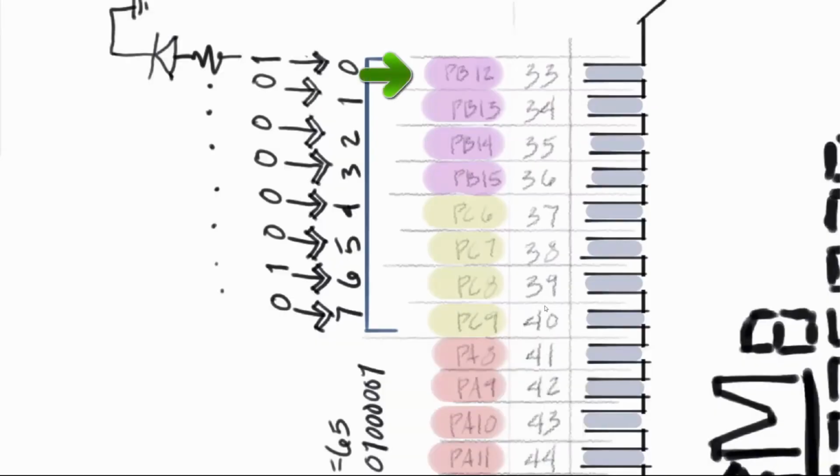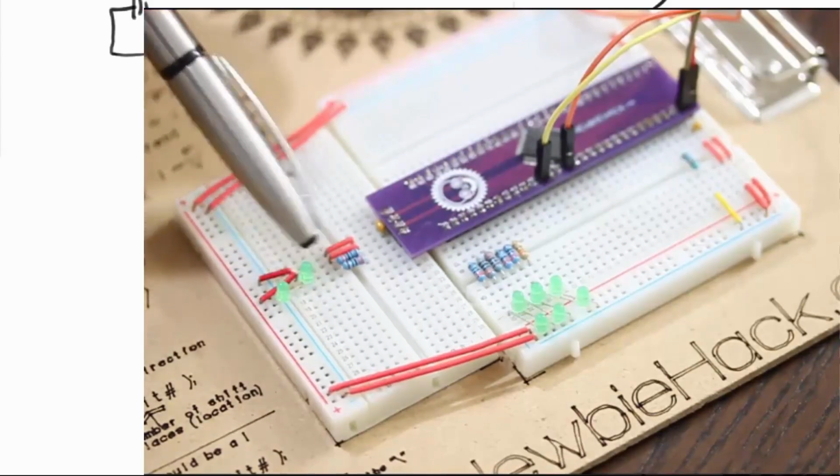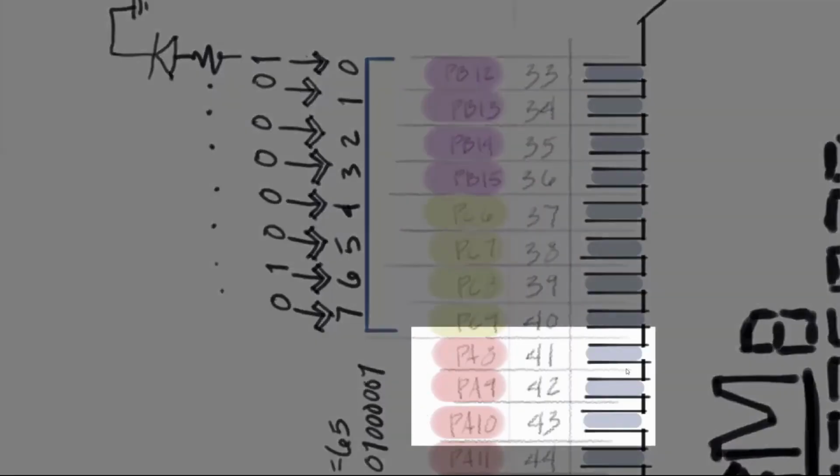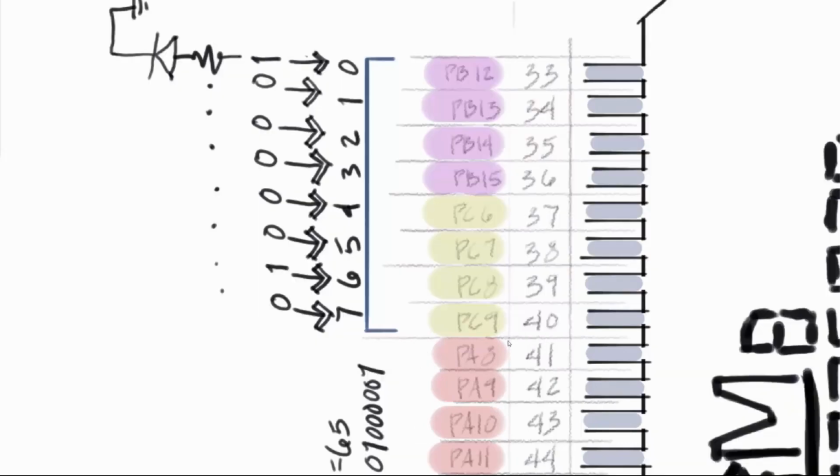And 33 is at this location of the breadboard, 33 and 34. So we'll need 3 more pins. And I think 41, 42, and 43 would be fine since they are also the 5-volt tolerant pins. I'm going to go ahead and apply some LEDs to those pins, and then we can test the enable, read write, register select, and the byte again.